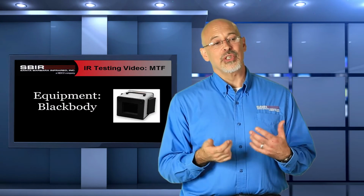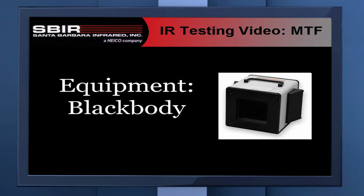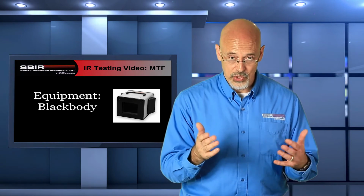Once again, we come back to needing that black body, a calibrated source so we know the temperature that's put out. What's interesting is that we don't really need such precise calibration on that black body. We just need an effective step. We want the step to be within the linear range, going all the way back to the SITF function. We use that to determine what the temperature is that we want to set. We don't want to saturate the camera. We want to be in the linear range of the camera to produce that curve.